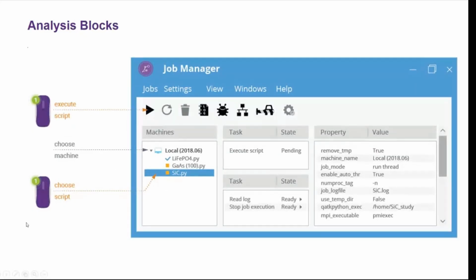Once you put the structure into the simulation, it will come here as SiC, and then you have to click on this execution button. Once the execution button is clicked, it will go into the simulation process, and you have to wait for the result. How will you identify whether my simulation is done? You can identify it with this check mark. You can see it here, this one is a rectangular box. Once it is finished, it will turn into a right tick. Once it is converted into the right tick, that means the simulation is completely done, and the result will be shown in the left floor.